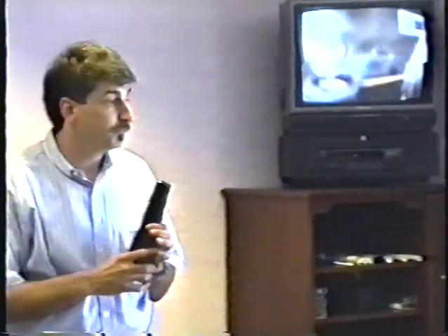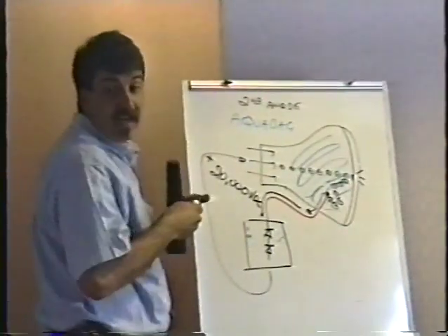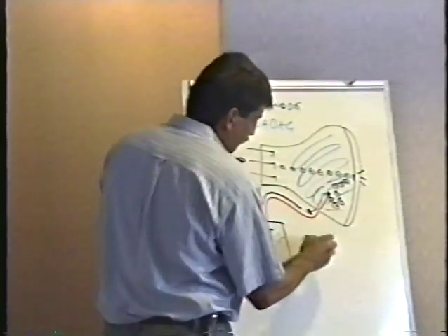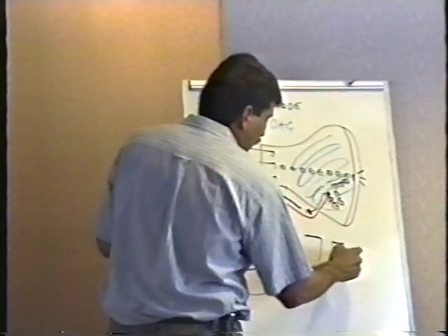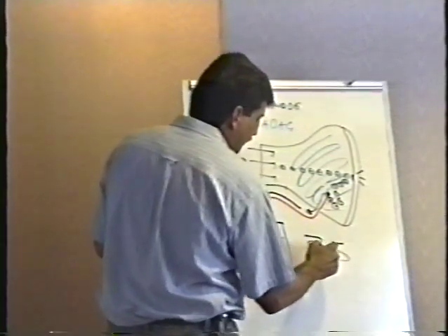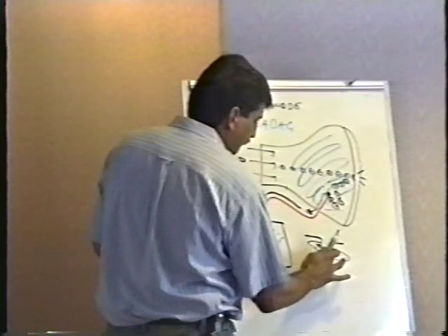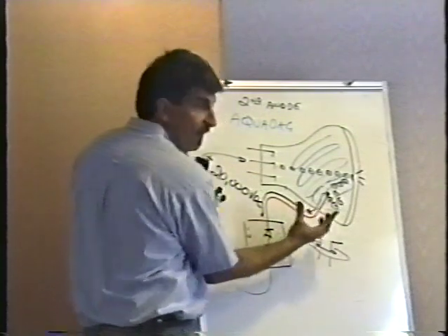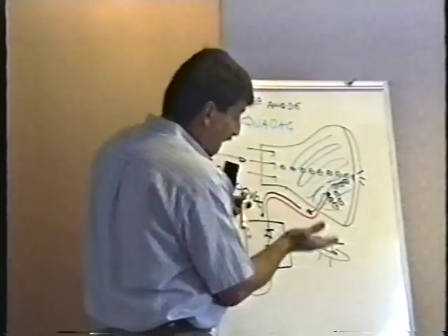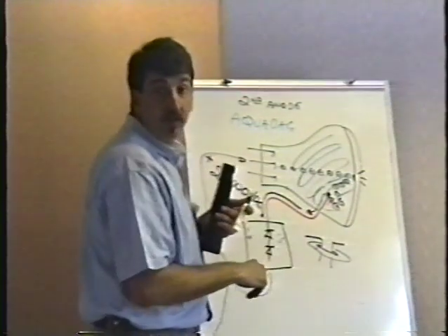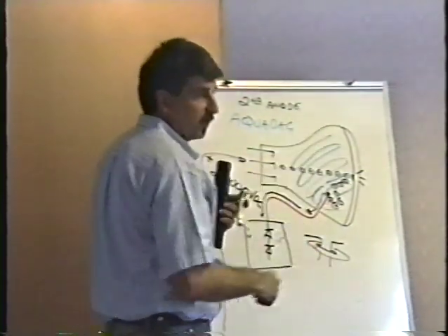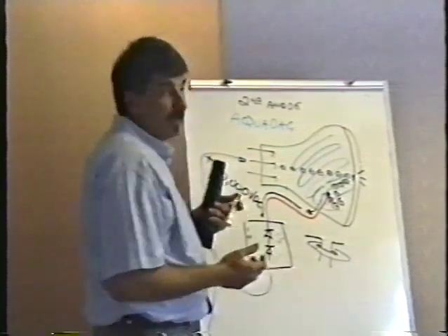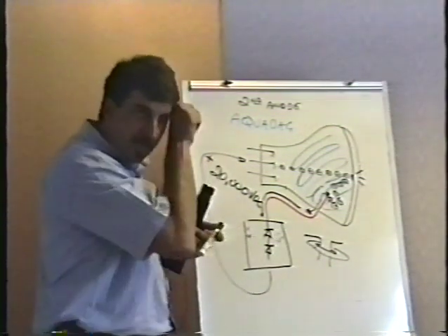Okay, so that's really important. Yeah, Jeff? I noticed that one had like a little washer on there. Yeah, some of them do, and this is kind of a pain in the butt. Some of these second anodes, here's the two little fingers, and they've got a washer like this with a slot in it. I assume that washer is to keep the fingers together and to keep it solid and to make good contact. It makes it really difficult to get that thing in there. Some people pull the washer off and throw it away. I can't say that there's anything wrong with that. I don't, but it sometimes makes it kind of a pain in the butt.